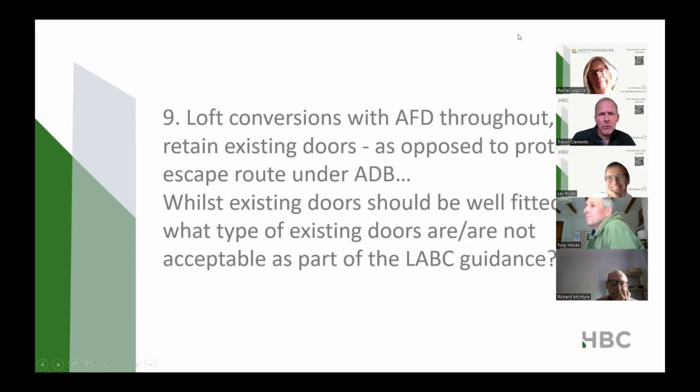Loft conversions with automatic fire detection throughout, thus retain existing doors. Right, well, this is loft conversions. Usually you have to create a protected escape route, don't you, from the stairway? There's this option that has come to the fore, that rather than swap out the existing doors for fire doors, FD20 doors, you can retain the existing doors and then just put this enhanced L1 fire detection and alarm system to compensate for that.